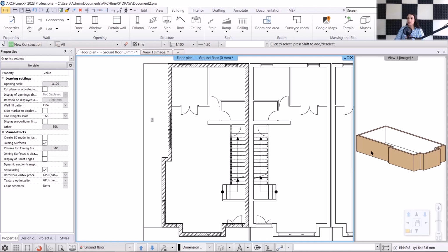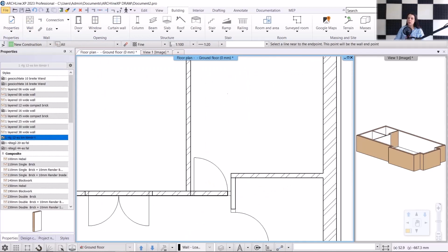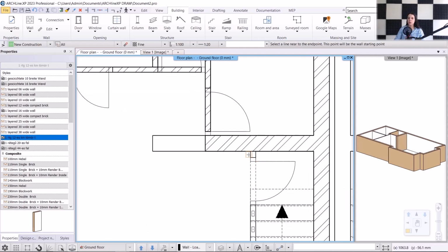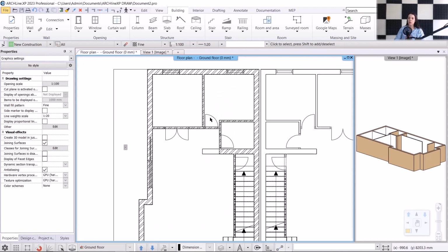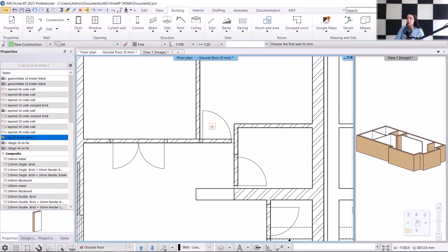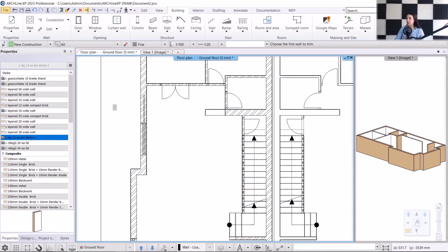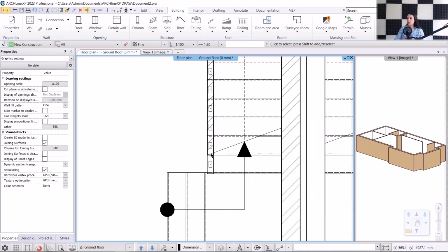Let's create the partition walls, as well, using the same command as before. After completing those tasks, we need to create the T connections as well. For T connections, it's essential always to specify the stem of the T first, followed by the top. This way, the program will connect them properly. Done. Now, I need to modify the length of this wall section. I click on the wall, choose the arrow, and can easily extend it.